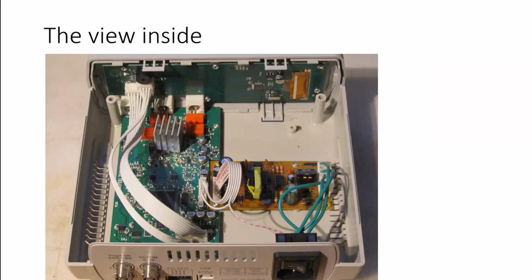And if you look closely, you can see that there's a multi-strand wire, a little ribbon wire, that goes between the power supply and the main board, and that one of the power supply lines, one of the ground lines, has been cut out and moved over and soldered to the earth of the main socket. So that's already been done on this board. That was done by the manufacturer, it wasn't done by me. It was like that when I got it, apparently, because this is the first time I've opened it.